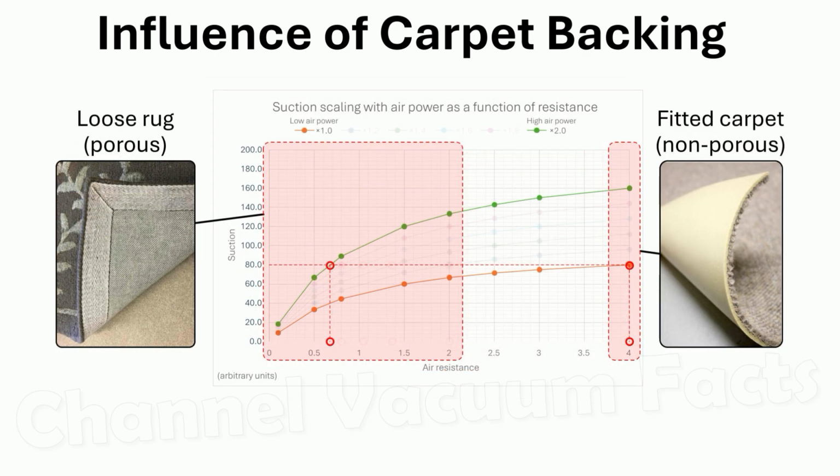Motors offering sufficiently high air powers with enough air watts help sustain suction pressure and therefore airspeed in the presence of larger leakage airflows to achieve faster cleaning. This is why it can be helpful to use boost mode to clean heavily soiled rugs.